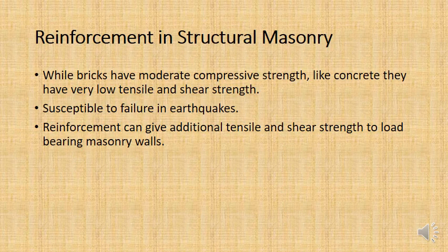So let's talk about reinforcement inside structural masonry. As I said before, most bricks, most masonry blocks, have very good compressive strength, but very low tensile and shear strength. Well, with a building, if it's a wall, it's mostly going to be under compressive loads.